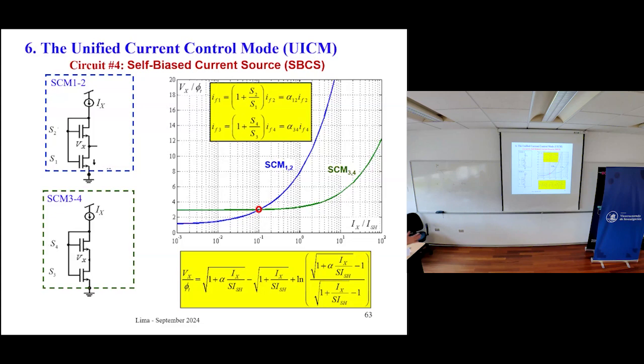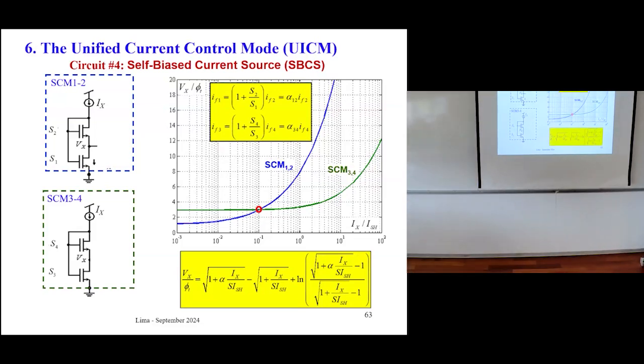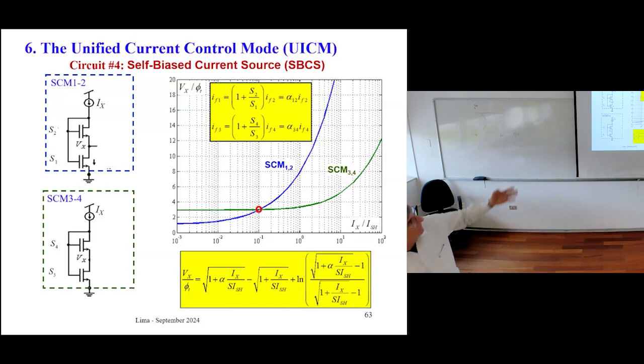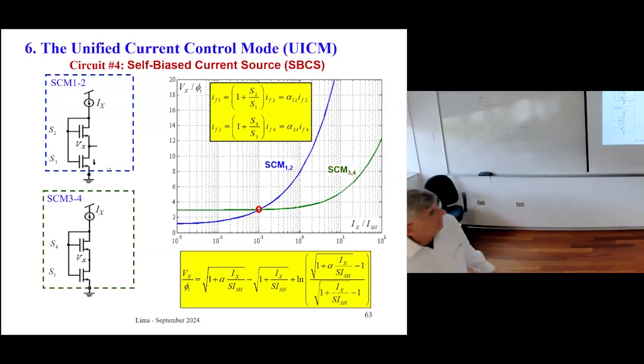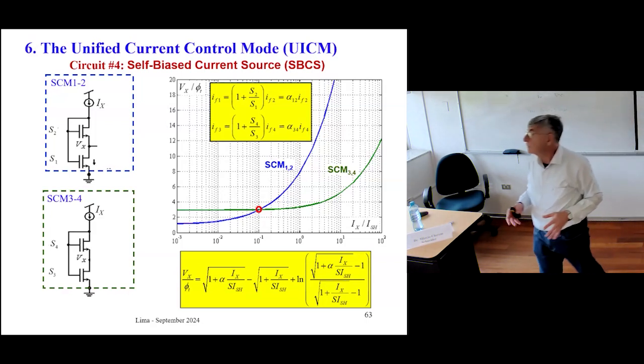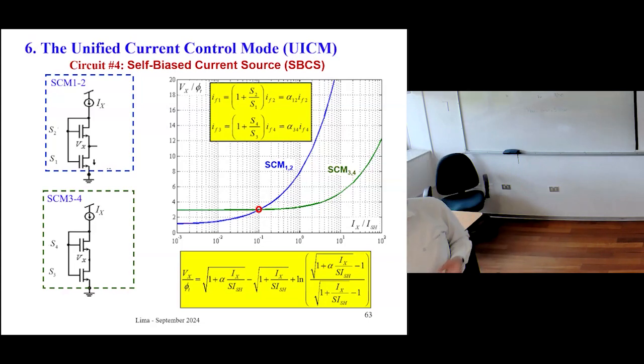We are seeing here a way to generate a current which is a replica of the chip specific current of the MOSFET. Of course, there are several ways, several geometries. It depends on the current that you want and on the voltage that you want, but you have equations, you have a way to reach the current that's needed for your design.